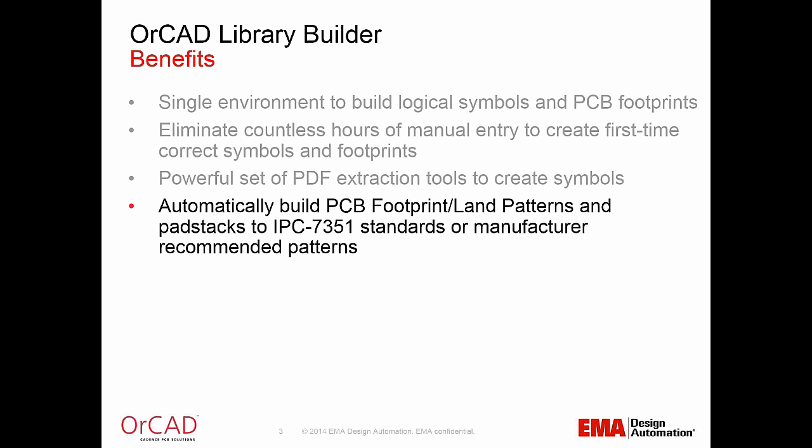Having been a designer for many years myself, one of the most difficult items in building a surface mount footprint is determining the correct pad size, the toe, heel, and side adjustments to match the physical pin on the package that will meet your manufacturing processes. With OrCAD Library Builder, we have powerful algorithms that automatically calculate the pads per IPC 7351 specification.